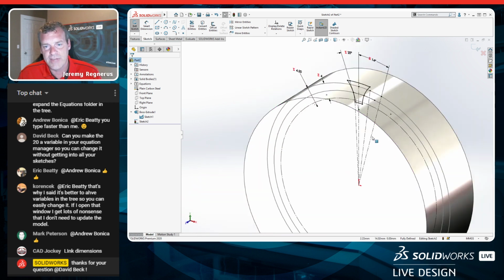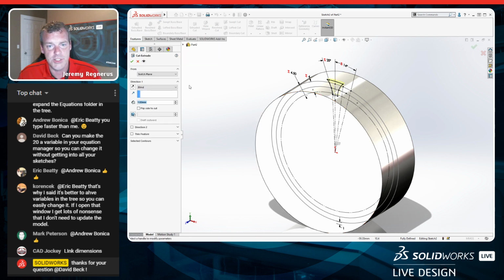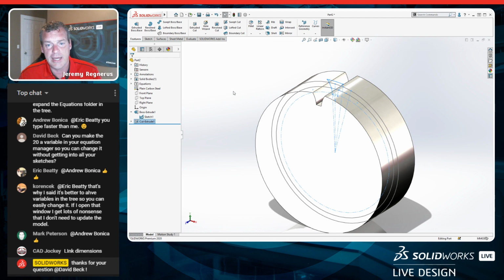All right, so we've got our sketch. What's next? Let's simply cut it. Let's go up to our features, create a cut extrude. We're going to choose through all in both directions. I just want to cut all the way through this thing. Hit OK. And there we go. We've got our cutout. Everybody can probably guess where we're going next, what the next feature in the feature manager tree is going to be. Circular pattern, maybe.